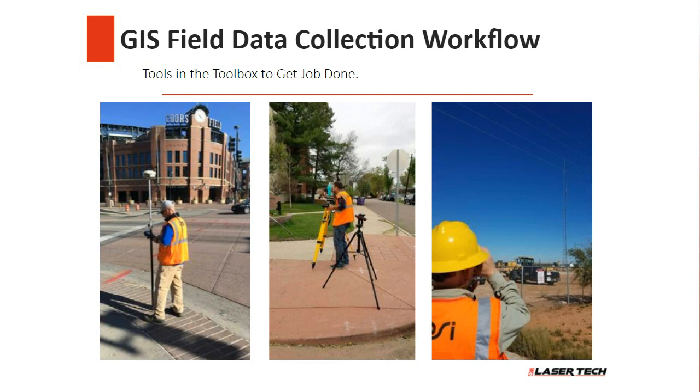So in this picture that we show here, it's highlighting that we're trying to utilize the best tool for the job for what we're trying to accomplish. In a lot of cases, physically occupying the point is the quickest and most efficient way to capture something, or an asset, for instance, on the far left, where we're capturing a property pin, a location for a property corner, or in the center, where you've got safe, easy access to that, right, Mike? And you might have to read a tag number off that pin anyway.